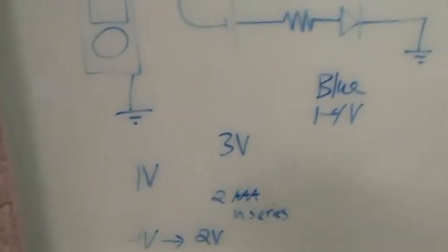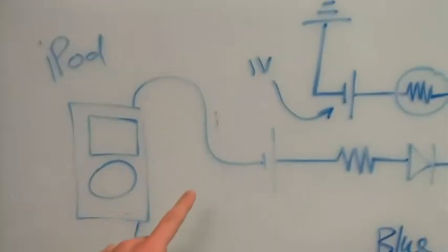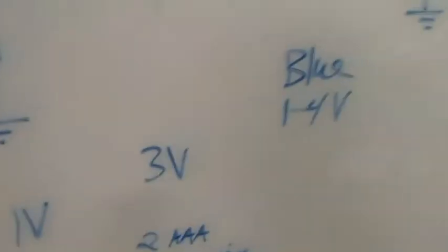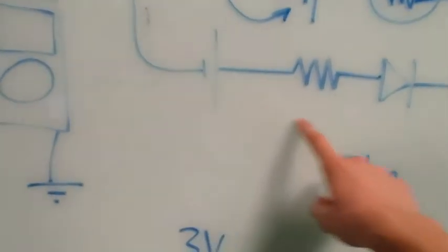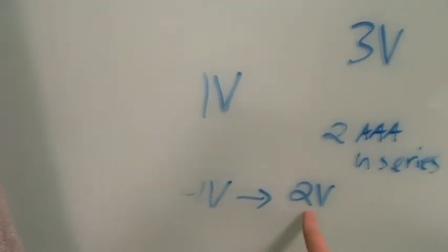And so the idea here is that your iPod will generally output about 1 volt at its peak. And so if we plug the iPod directly into about a 3 volt battery, which we can get from about 2 AAA batteries in series, you'll see that we then funnel that higher frequency, which will peak at about 4 volts, and then the negative 1 volt minimum in that iPod signal will be about 2 volts.